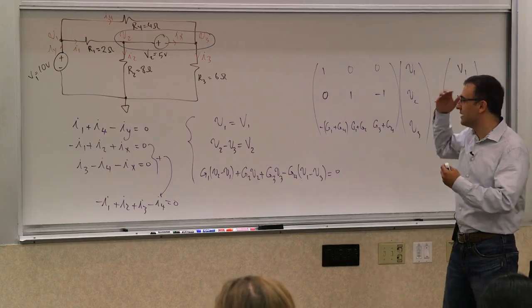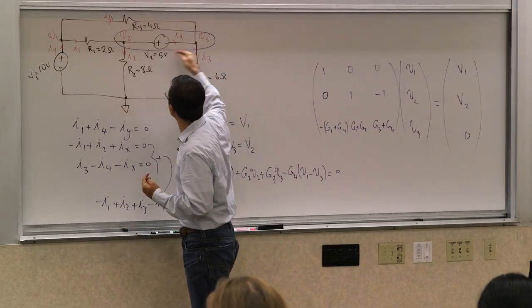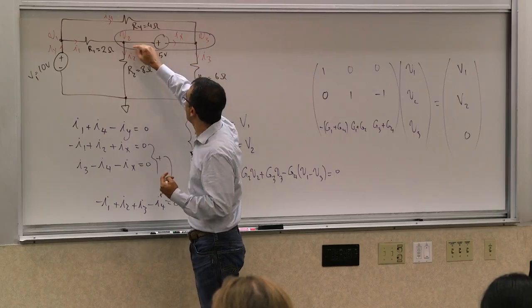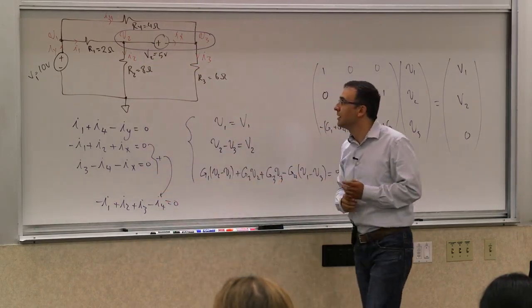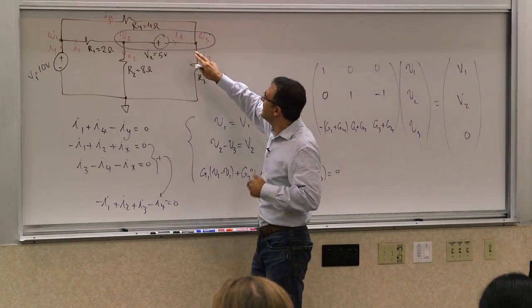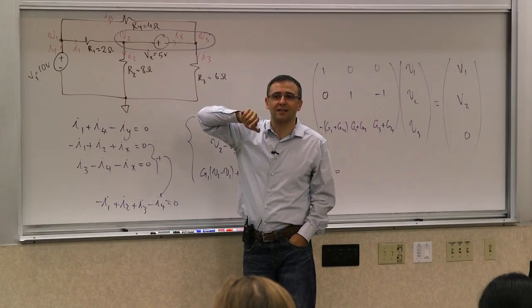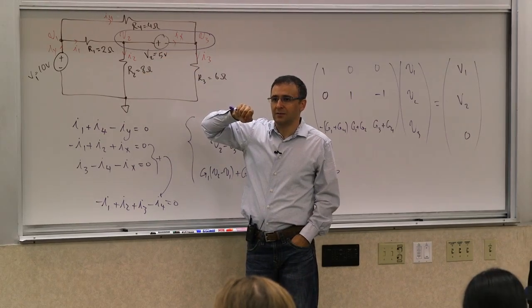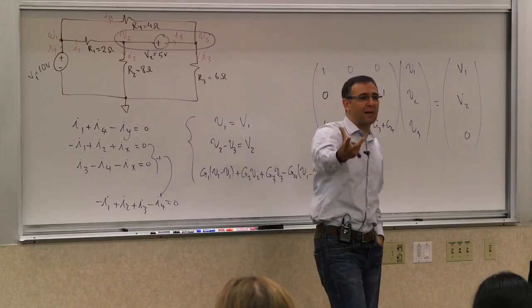So I didn't need to write all these equations and convert them. I have a voltage, so I define a supernode around it, and I write the currents that go into the supernode. And that gives me the equation I need, because it really doesn't care what is the current flowing inside that node, that Ix. It becomes unimportant. It's inside the black box.